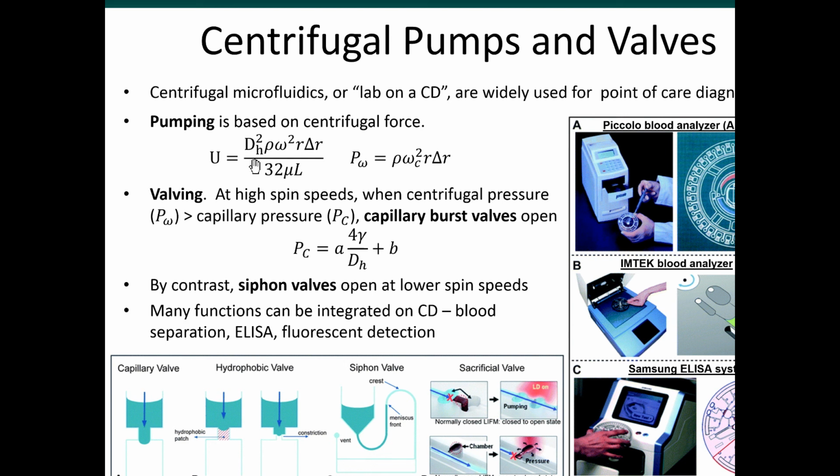In microfluidic devices, we always talk about low Reynolds number, which means inertial effects are negligible compared to viscous forces. However, these disks are spinning very rapidly, like 3,000 RPM, 1,000 RPM. When the disk is spinning that rapidly, you are generating significant centrifugal forces, significant inertial forces, and that can then be used in microfluidic systems.